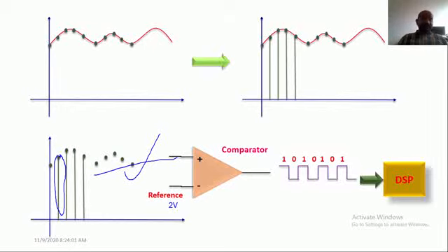Let us suppose this signal amplitude is, for my calculation, 1 volt. So the comparison is between 2 volts and 1 volt. The comparator computes 1 minus 2, which is obviously minus 1, so I show it as 0 volts because it is not positive. Because the input signal voltage is not greater than the reference voltage, I am using the comparator in such a way that the output should be 0.